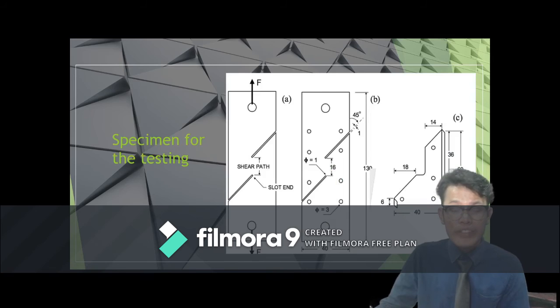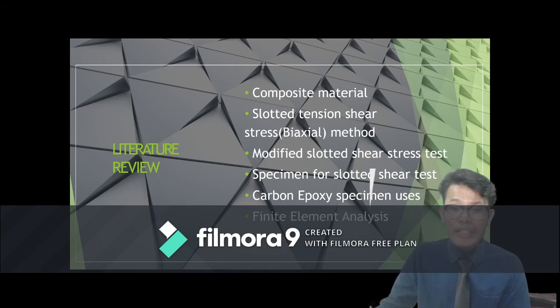For the specimen size, the picture shows the basic model. I will draw it in axis for the 3D model. For finite element, I use ANSYS software to simulate the project. The precision of this method can be improved by increasing the mesh density, that is, increasing the number of finite elements used. This will make the simulation result look like the actual physical structure.